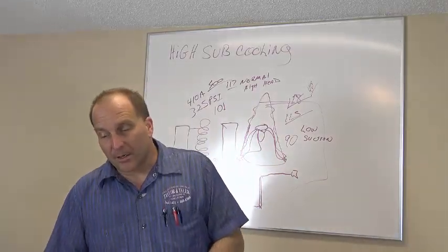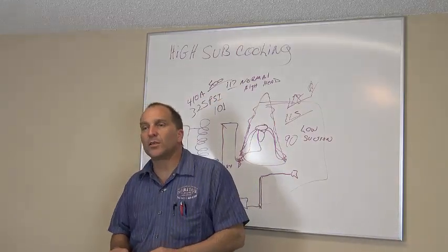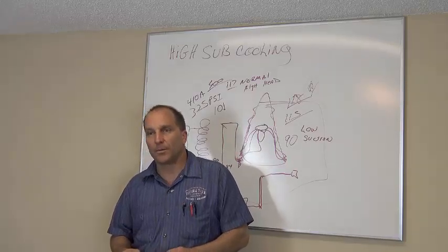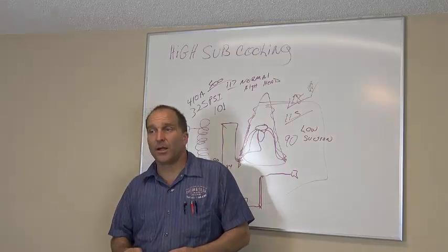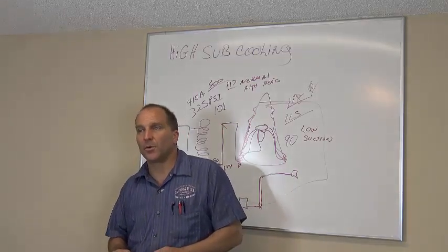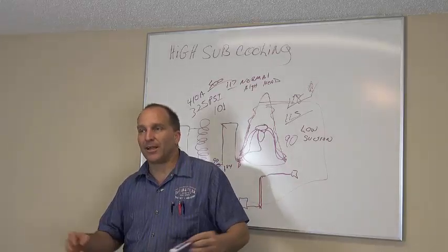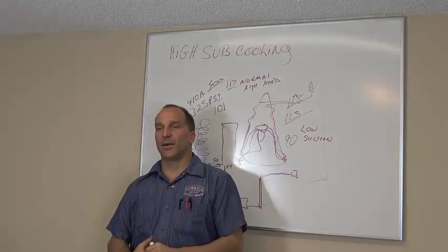What if you take a hose and you go hose the condenser down? Will that give you a high subcooling? Water, just add water. Just spraying it down with water will give you a high subcooling, because you are taking the heat out of the condenser. You are subcooling the refrigerant down.